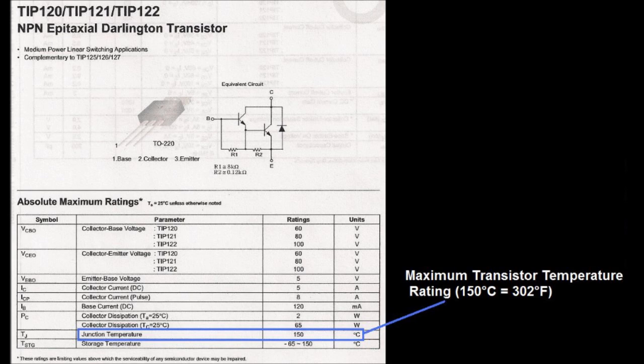That's pretty hot. Well, if you have your heat sink attached, remember, if you haven't seen it, go ahead and watch it. I did the digital multimeter tutorial part 2, which uses the temperature probe. The temperature probe comes in handy to monitor your transistor to make sure it doesn't overheat, because this shows the maximum temperature of 150 degrees centigrade. As long as your transistor stays below that, then it will operate fine. So keep that in mind.